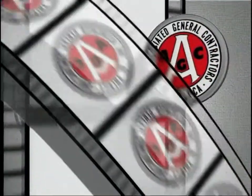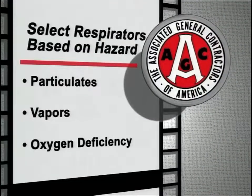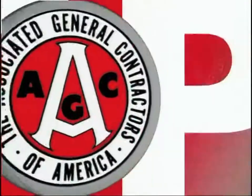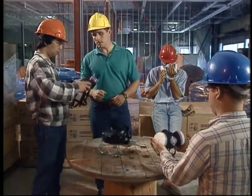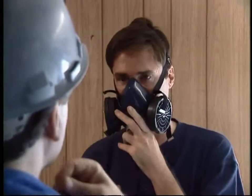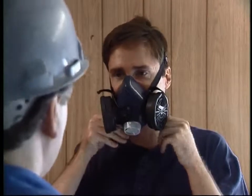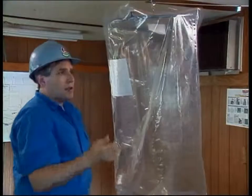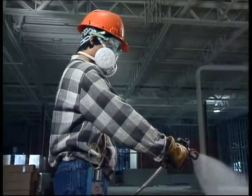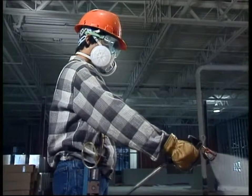Select respirators based on the hazard to which you will be exposed. These hazards include particulates, vapors, oxygen deficiency, or a combination of hazards. Use a respirator only if you have been trained in proper use, maintenance, and limitations. Fit test respirators prior to initial use and at least once annually to make sure they seal to your face and that there are no leaks. A proper fit is essential for respirators to be effective.